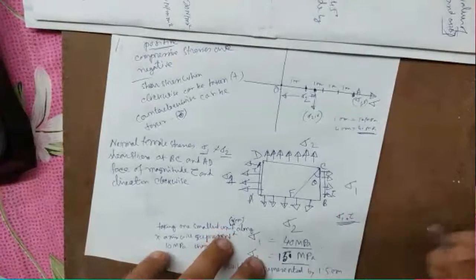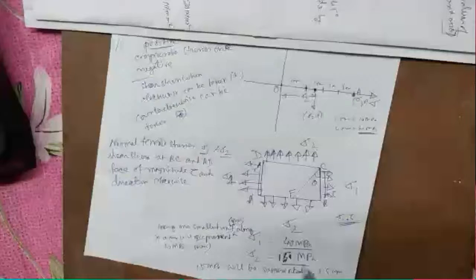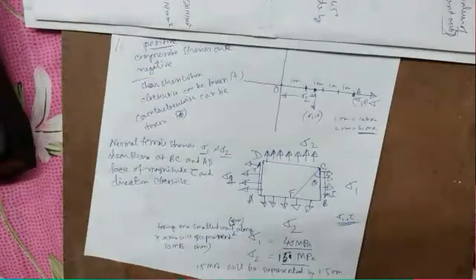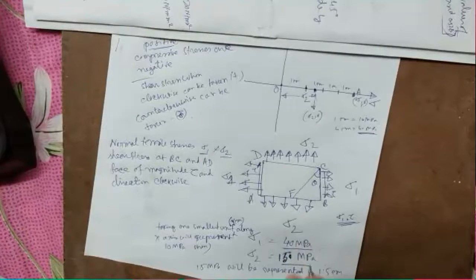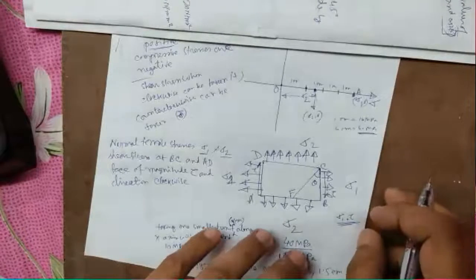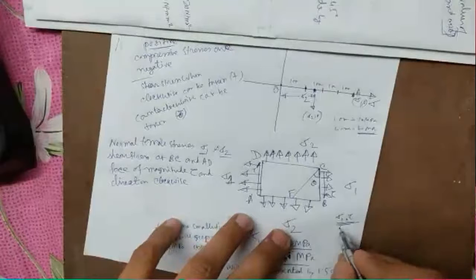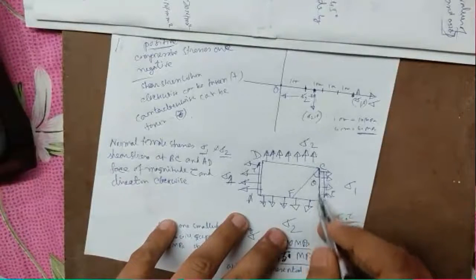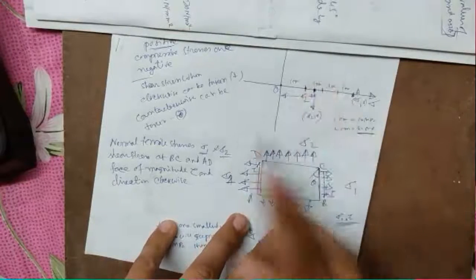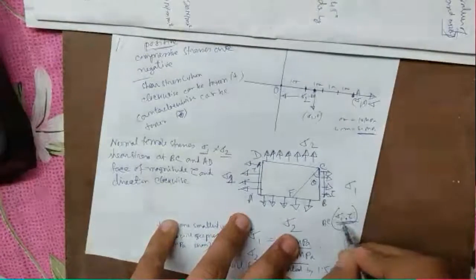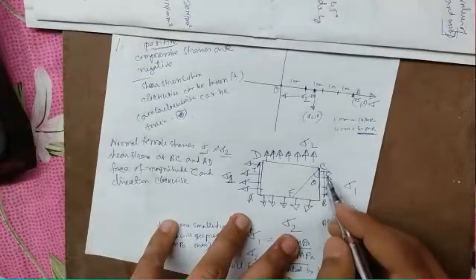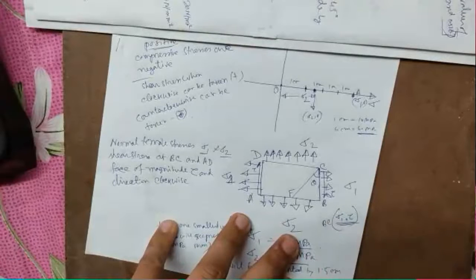Now in the Mohr circle, all the planes are actually shown by a point, on the periphery of the Mohr circle. So this BC plane can be denoted in this coordinate system by the coordinate sigma 1 comma tau, where clockwise is taken positive.